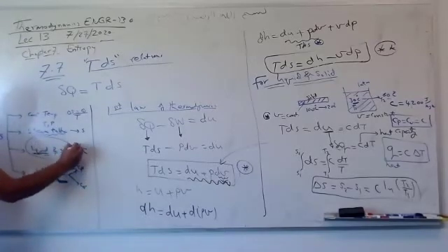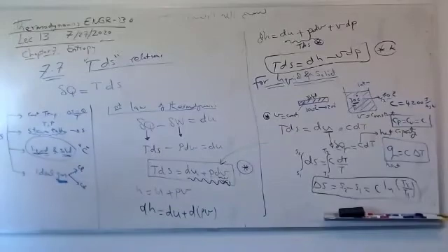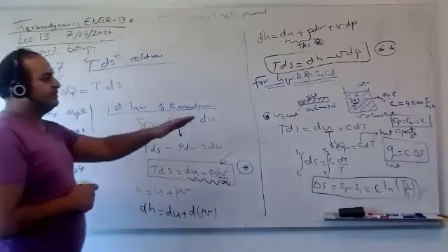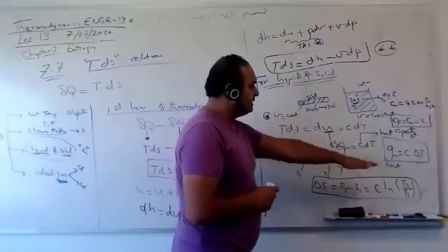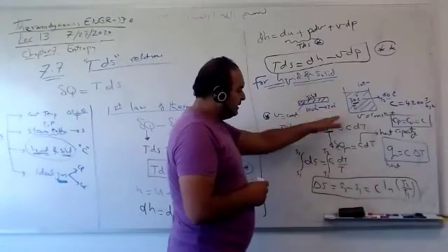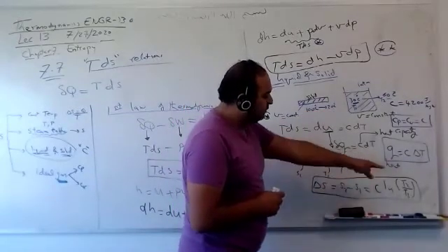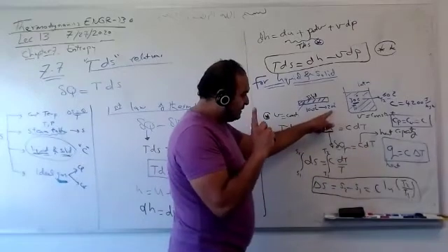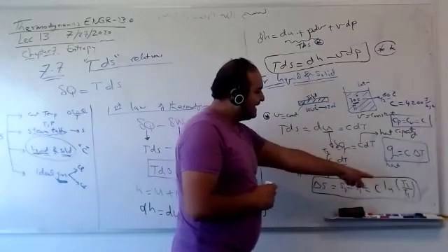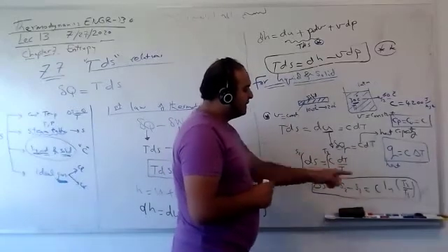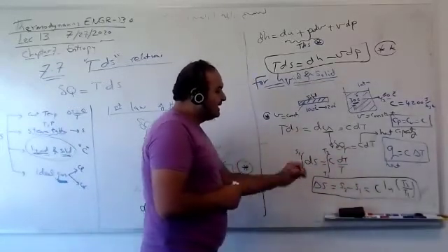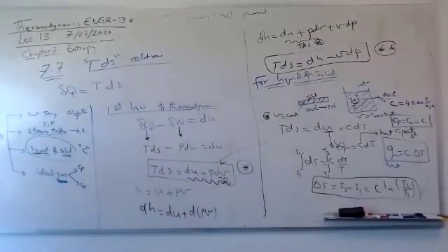But for solid, we have just one C. So if I ask you in the exam, I want delta S for pure aluminum, pure copper, pure water, with heat addition or heat rejection, you have initial temperature, final temperature, C then. If this cools down, this delta S will be negative. So T2 over T1 in Kelvin, ln of T2 over T1 less than 1, it's negative, times C, which is constant for this material.